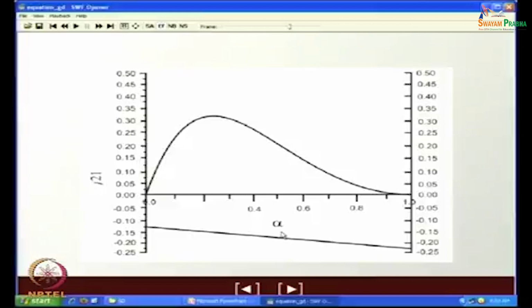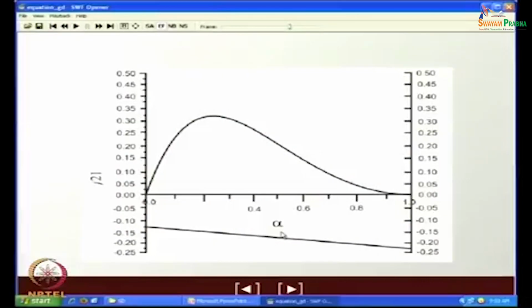Quite expected. Have you ever found any counter current operation with gas down, liquid up? This cannot be a stable situation. We cannot have anything where the gas is going down and the liquid is going up. Counter current means gas up, liquid down. Okay? So, from this particular curve we find that such a situation is not possible, which you already know.